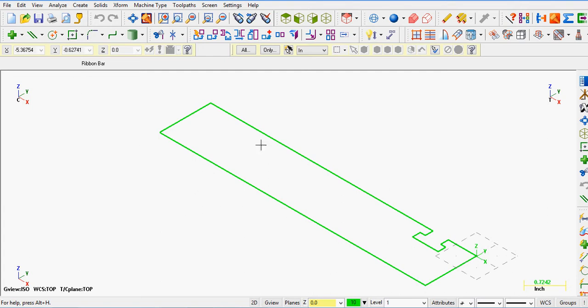So here in the drawing window, our graphics area is where we're going to create our graphics. I'll activate the commands using one of the toolbars or the drop-down menus. Okay. What I always want to pay attention to is the status bar across the bottom, which lets me know I'm in 2D or 3D drawing mode. Just by clicking on this, I can change it.